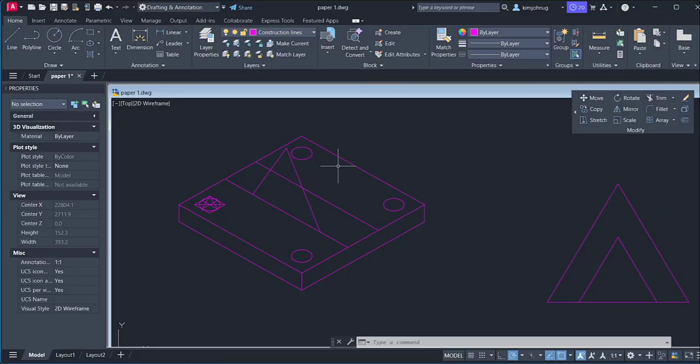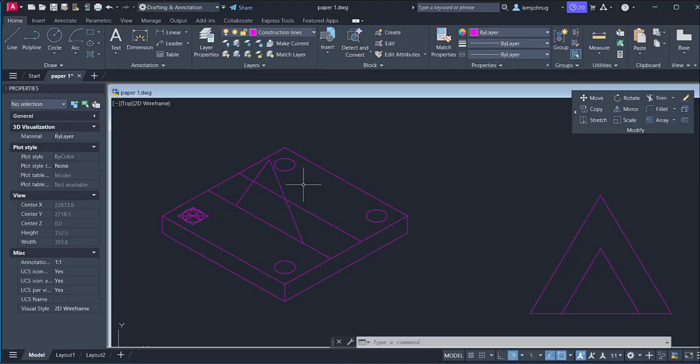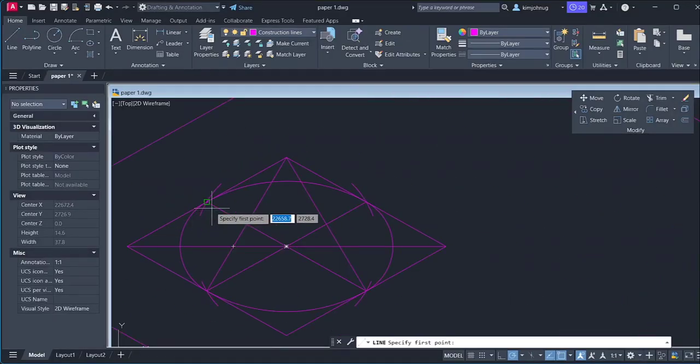So with that done, what else do I need? I have a bracket on top that's going to host the bearing. It's telling me from here that the height of this bearing is 40 millimeters from down, and it's in line with the center.